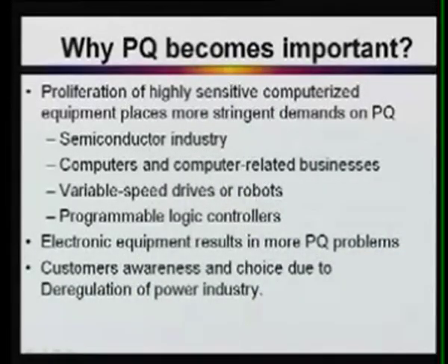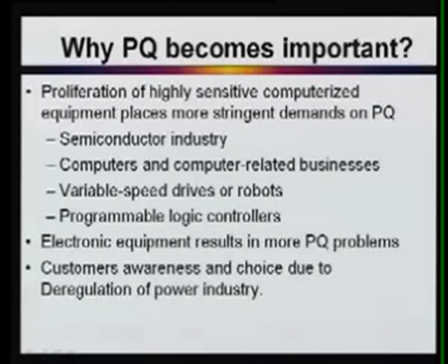We have to replace the insulator, and that equipment must be replaced. Similarly, phase angle displacement causes excessive heating of three-phase devices such as motors or three-phase rectifiers. If transients are there in the power system, they may cause tripping, component failure, damage to electronic equipment, and insulation breakdown of transformers and motor loads.